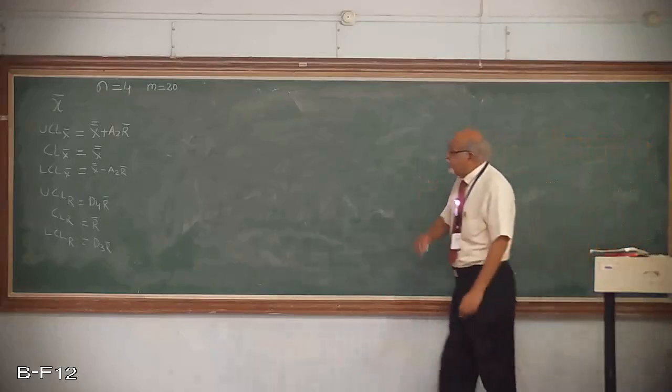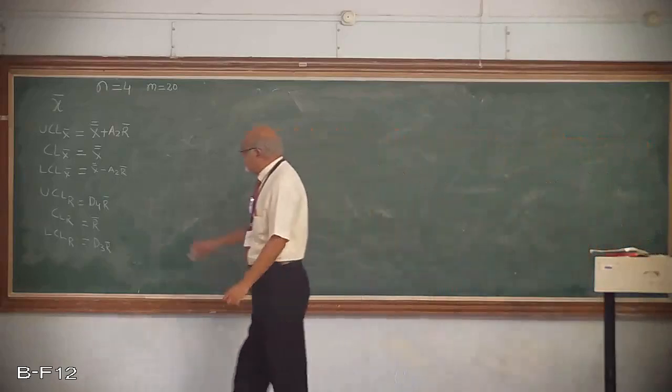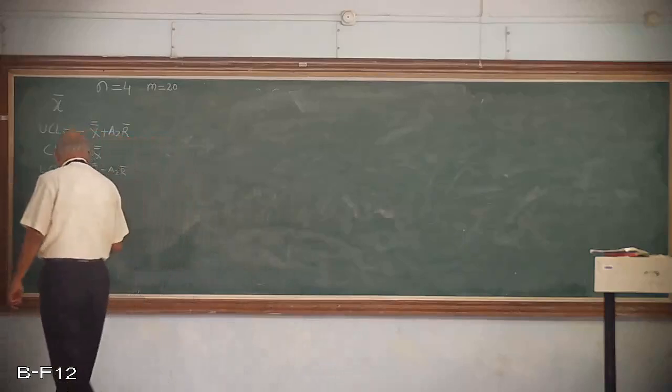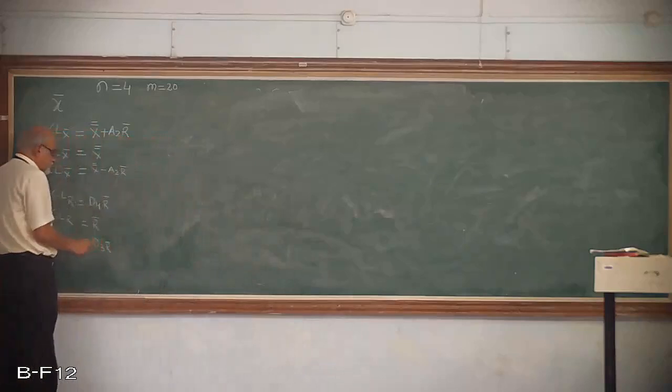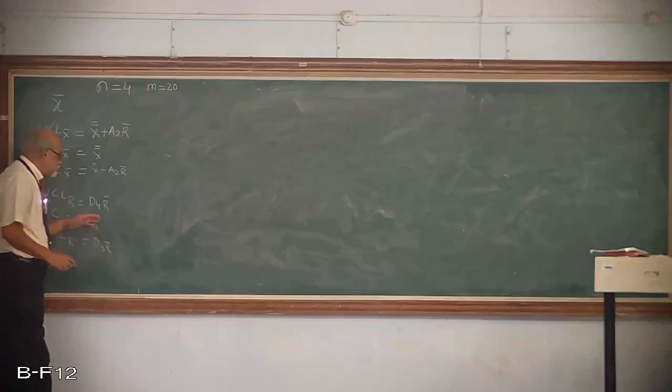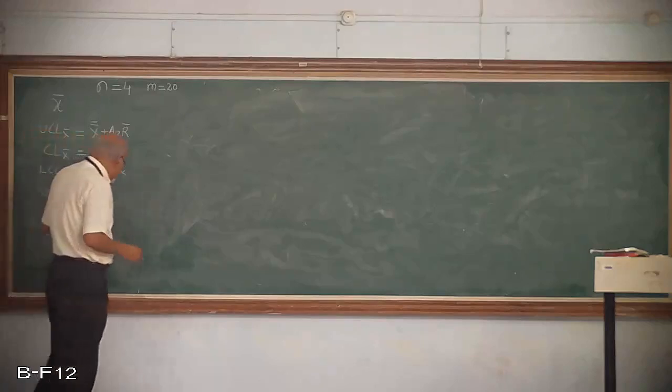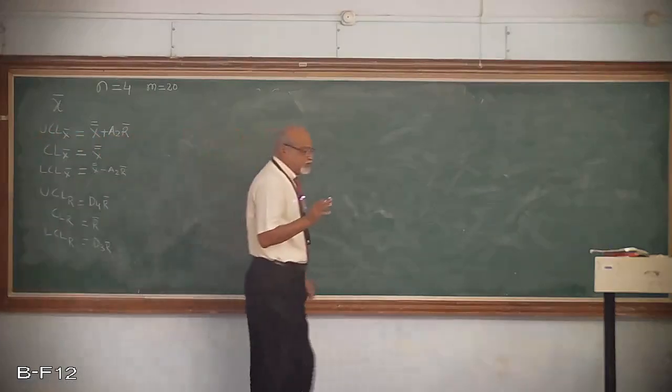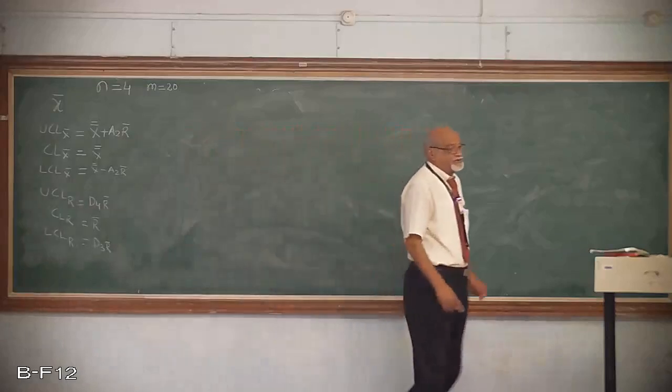In that table, you can observe that up to subgroup size 6, D3 is going to be 0. That means the lower control limit for the R chart, or the range chart, is 0. The upper control limit will have different values, so D4 values are given up to sample size 6.